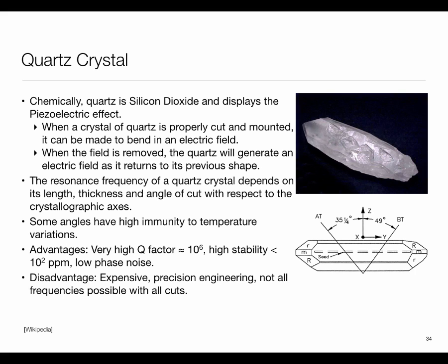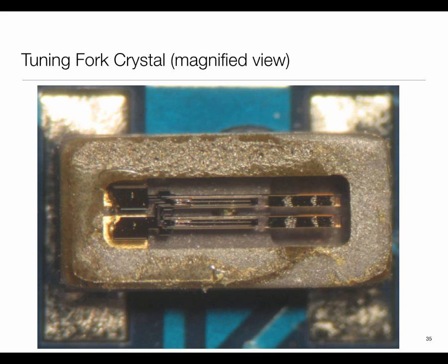But they again suffer from the same issue that this is a manufacturing process. You're taking crystals, cutting them, polishing them. So there are going to be variations, and there is, of course, still some temperature dependence also. Disadvantages: they're expensive because this is a mechanical fabrication process. The other issue is there is variation from crystal to crystal, and to get them very accurate, you need to do a lot of calibration. So they are kind of painful.